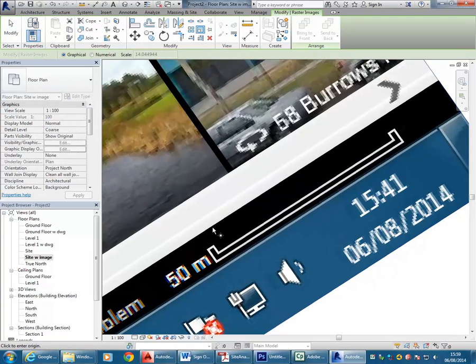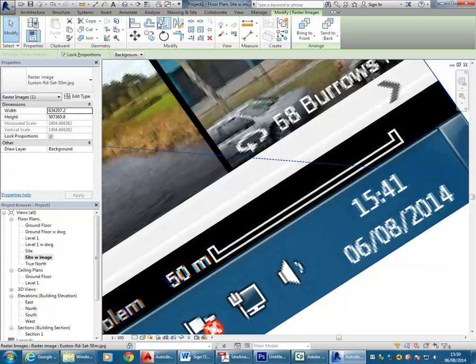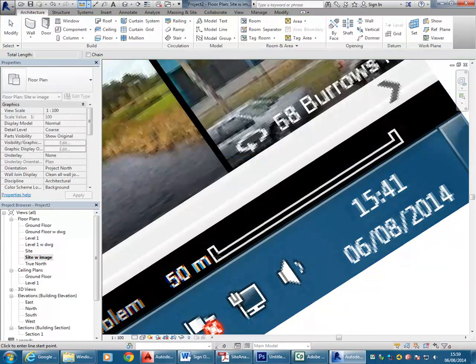I'll click the scale button, clicking on the centre point of the line, going to the centre point at the other end. And again, typing in, well, it was 50,000, so I'm not even going to change that. Just measure that again. Maybe my measurement was out. Yeah, look, that's close enough to 50 metres. There's no point scaling that actually.